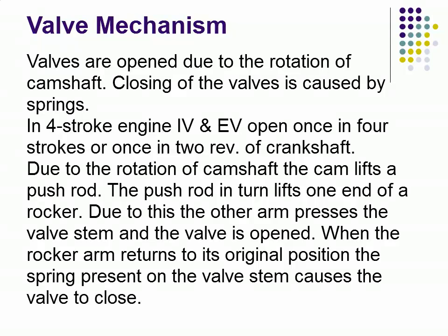Due to the rotation of camshaft, the cam lifts a push rod. The push rod in turn lifts one end of a rocker. Due to this, the other arm presses the valve stem and the valve is opened. When the rocker arm returns to its original position, the spring present on the valve stem causes the valve to close.